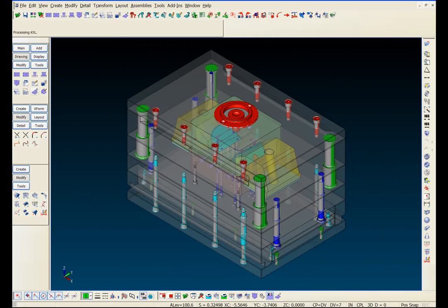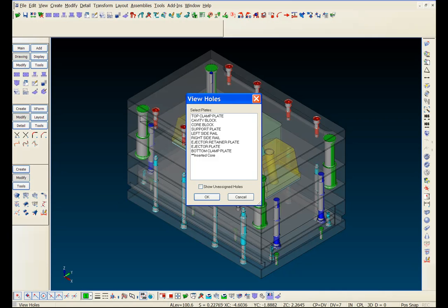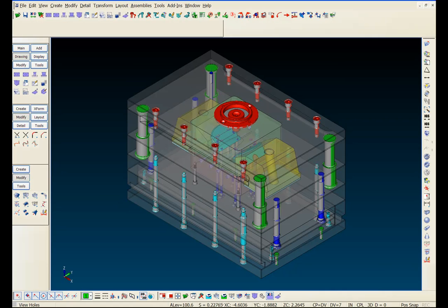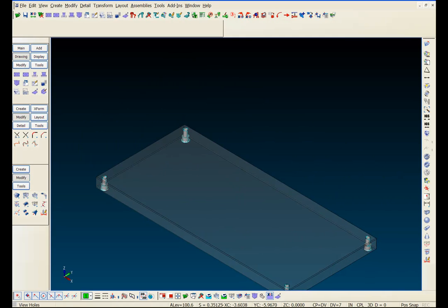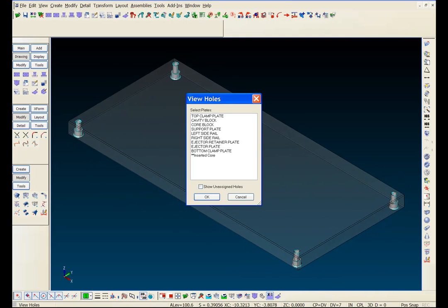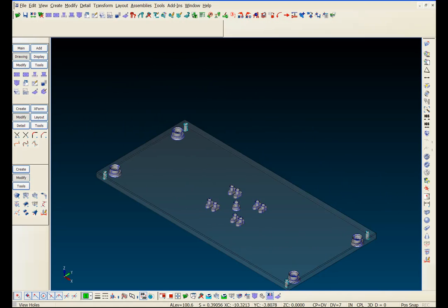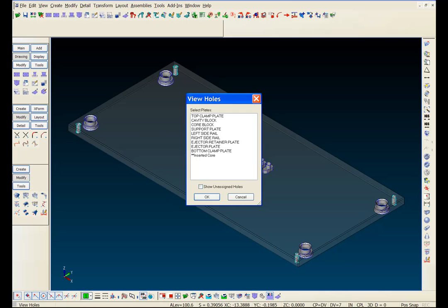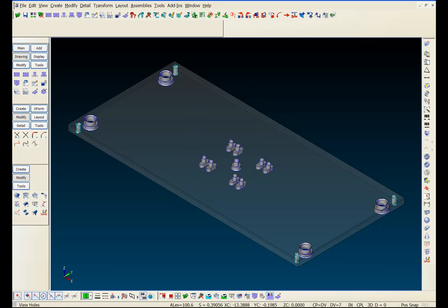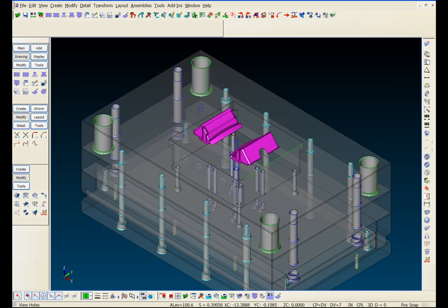You can see the 3D mold here build up with all the 3D components. I'll do a quick run through some individual plates. You can see my bottom clamp plate is ready to go. My ejector plate just has the insert screws in it, but that'll change. My retainer plate with the D-locks, return pins, and tapped holes for the ejector screws. And here's a build-up of the bottom half of the mold.